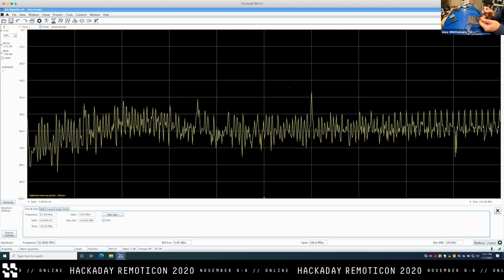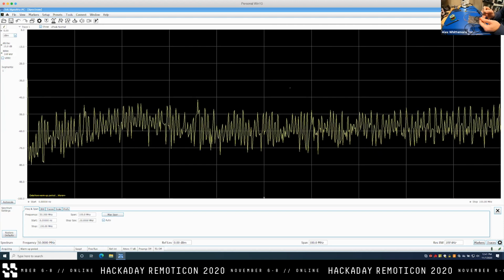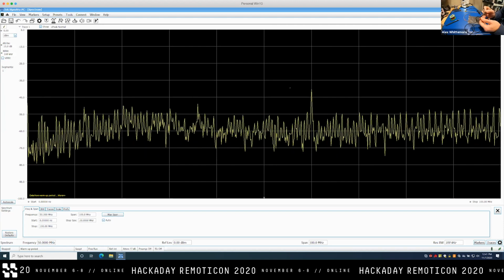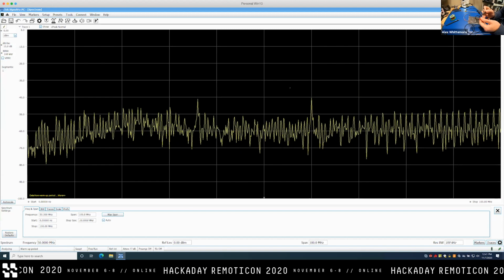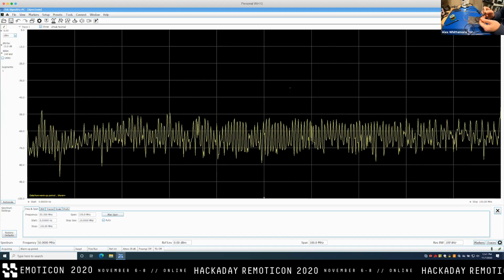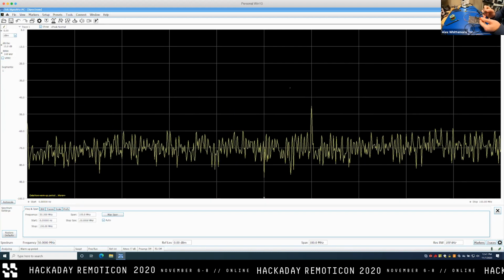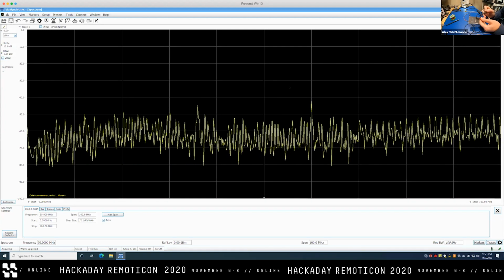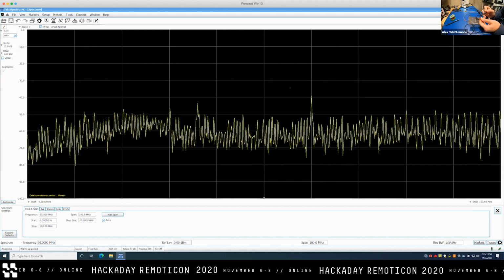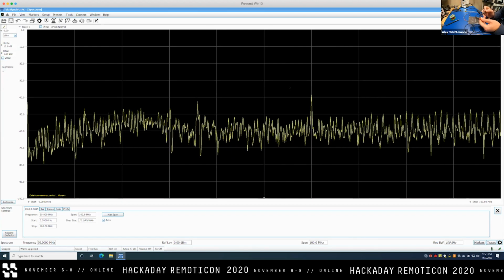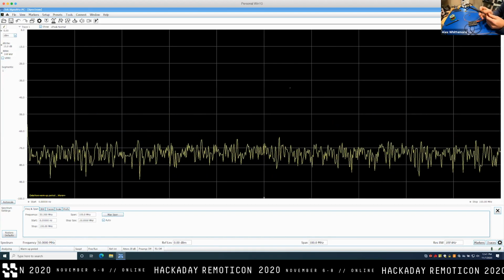And then if we come down here, we start to see a couple of other individual peaks. I see them now because I saw them earlier, but they are a little bit buried in the rest of the switching noise. So, okay, we've got some 60 megahertz somewhere over here to look into. We've got a little bit of peakiness down here. It looks like 35, 36 megahertz, something like that. So let's go in for a slightly closer look.